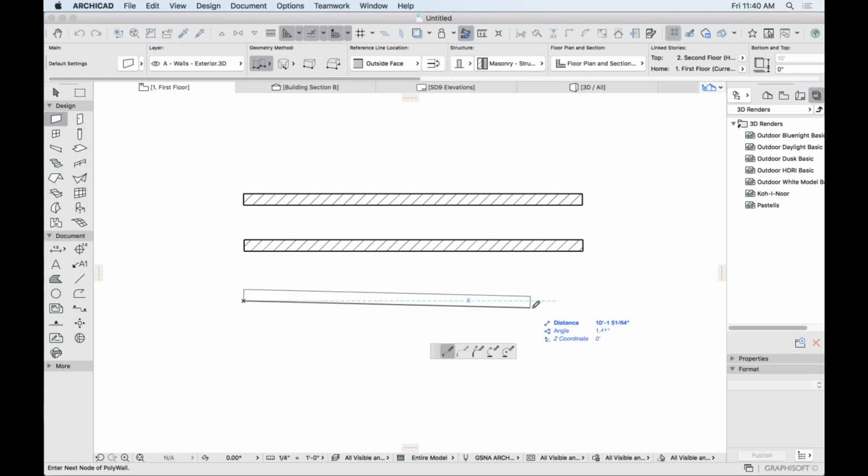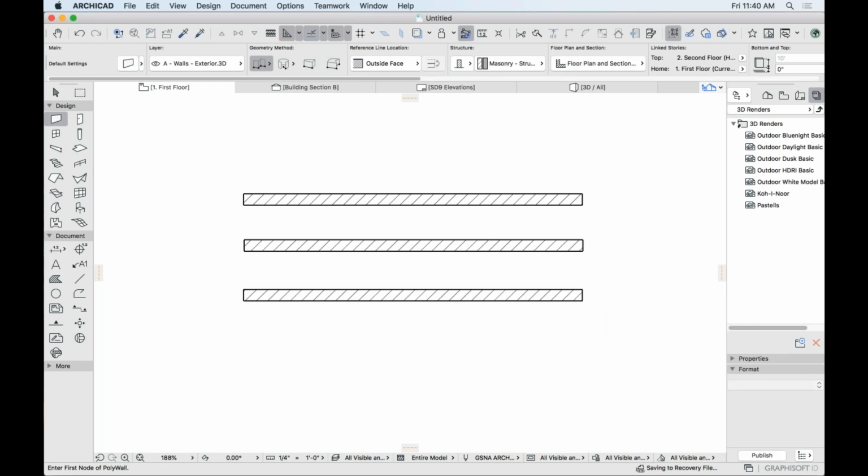And here's even faster than using the inch mark. Type in 144 slash. Slash, the little forward slash, the question mark. That is just a quicker way to do it because you only have to use one finger. You don't have to do shift apostrophe to get the inch marks. So you just press 144 slash enter. Then you can get your inches a little bit faster than having to do shift apostrophe.